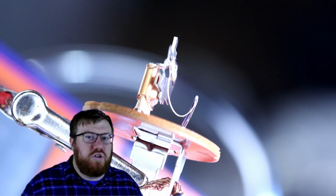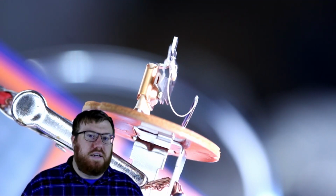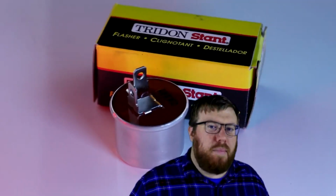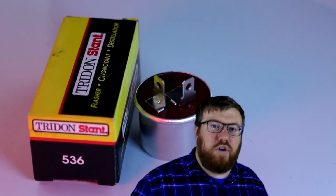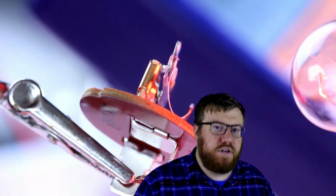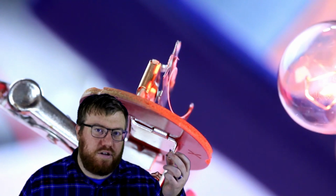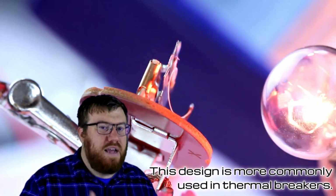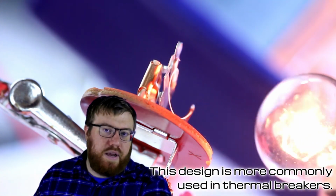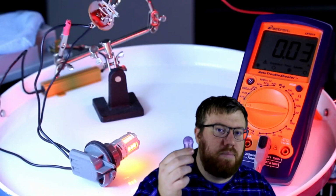With that extra amperage, you get more heat in that tiny wire, which means this heats up faster and turns on and off faster. One of the drawbacks to this particular flasher is that it has to warm up first before you get your first light out of your turn signal bulbs. There are some thermal flashers out there that also use a bimetallic strip like this, but instead of heating it up to make contact, heating it up pulls the contact away. However, both designs tend to not play very well with LED replacement bulbs.